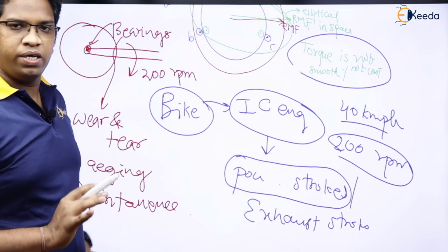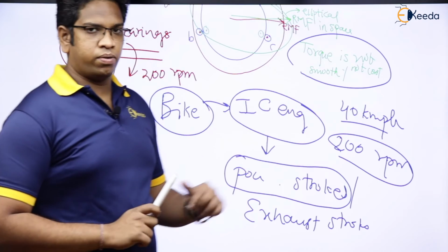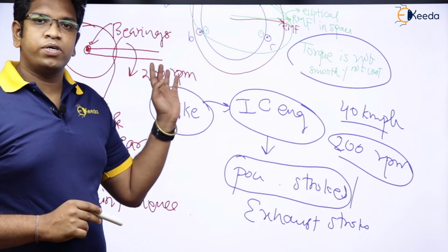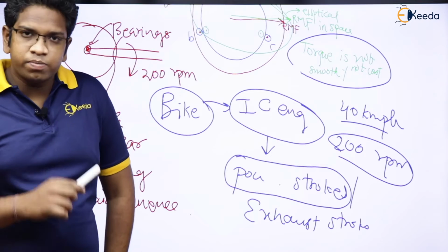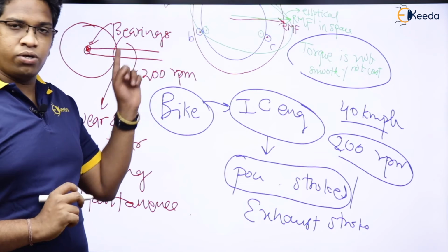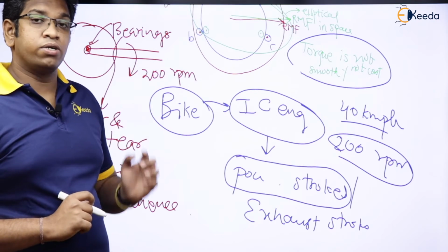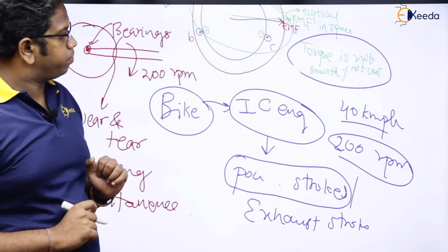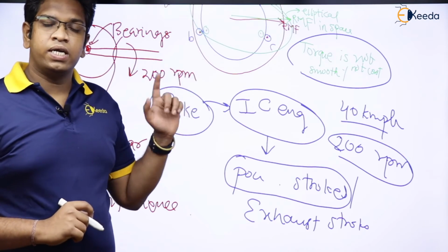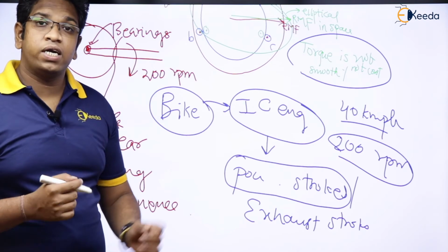So basically, if you think of one final thing, what is that? That torque is not smooth if my RMF is elliptical. And RMF is elliptical. Why? Because my generator is not supplying sinusoidal currents, or sinusoidal power. Then in that case, what is going to happen? RMF produced will be elliptical. That is the reason torque is not going to be constant, or we can say that torque is not smooth.